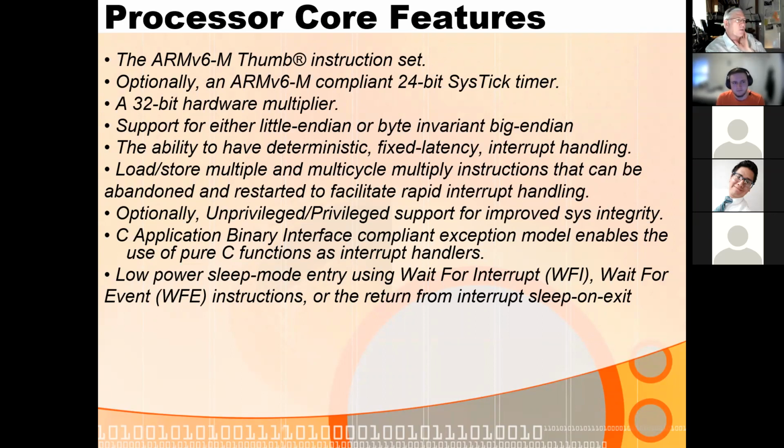And remember that if you have variable latency and there's jitter in how long it takes to get to the interrupt service routine and actually sample your input, what you're effectively doing is modulating your signal with your jitter, which is something you don't really want to do. So that fixed latency is really nice.